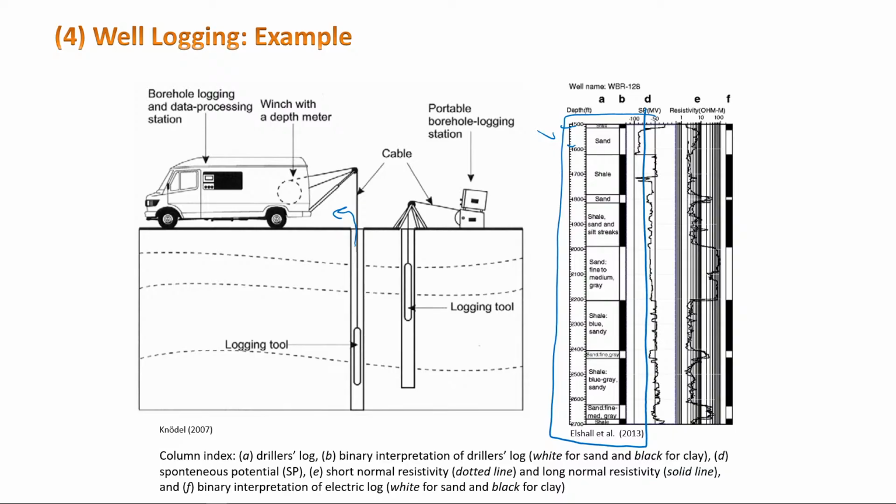Sometimes there are two types of drilling. There is regular drilling, and there is coring. Coring is where you get the core exactly intact. You try to drill in a way that you get the geological core out intact. But we don't generally do coring unless you have a specific purpose for it, because it is two or three or even four times more expensive than regular drilling.